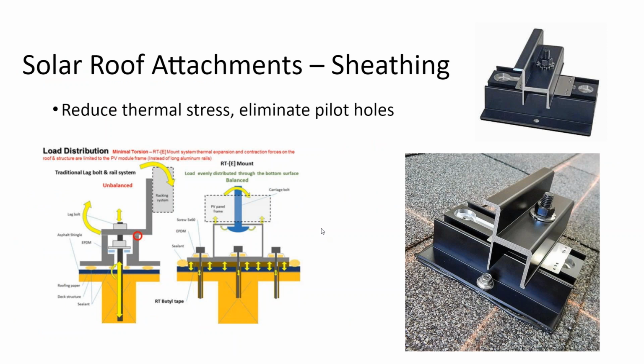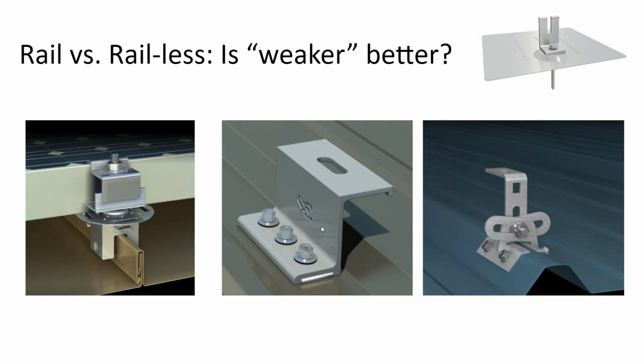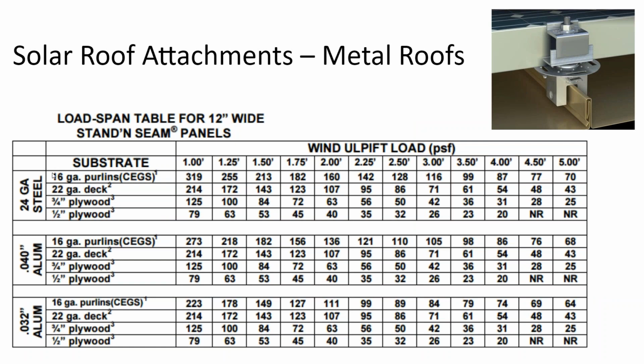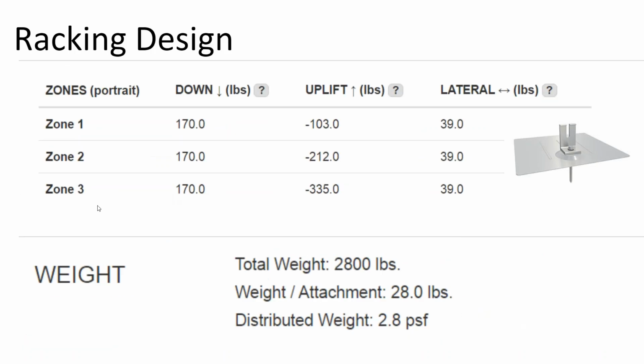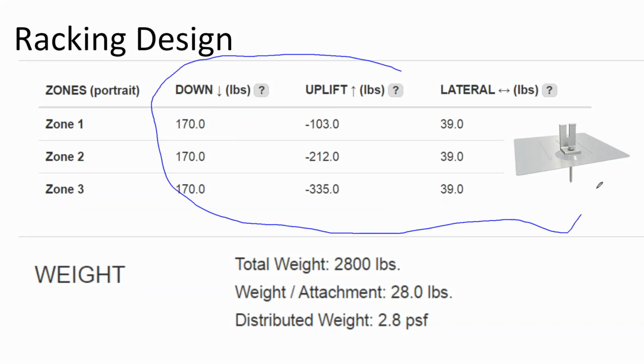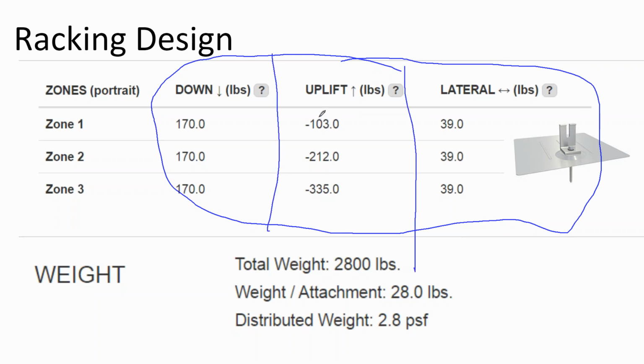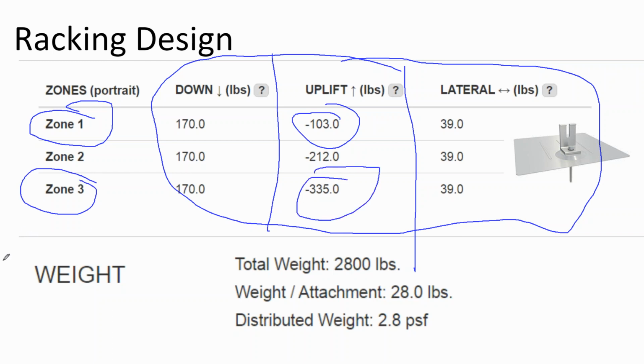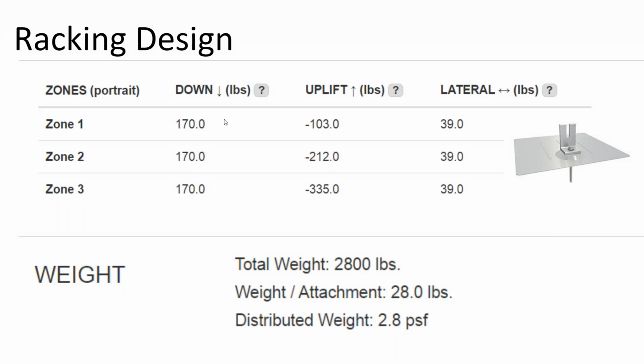this is a little bit more of a close-up, but ultimately, if you go through the racking design software process, you will get force load diagrams that will tell you how much force. This comes from the racking manufacturer after you input your system design into their sizing software. They're telling you the uplift force if you're staying in the interior of the rooftop is 100 pounds, whereas if you're at the edge of the rooftop at the corner, that same array would have a 300-pound uplift force.